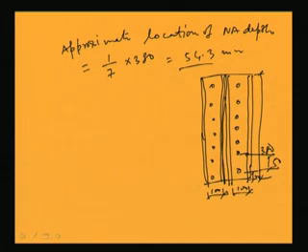So, this distance is 90. Now, neutral axis depth has been assumed at this point, that is 54.3, right. So, that means the neutral axis is lying above one rivet, okay. Above one rivet the neutral axis is lying at 54.3.